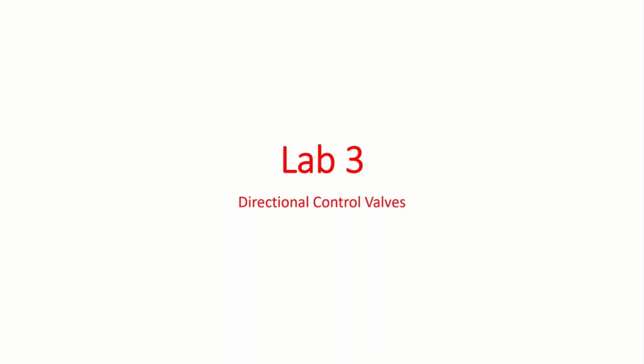In this video we are going to discuss valves with a special focus on directional control valves, and at the end of this session we will look at directional control valve inside FluidSIM, and we will design again a simple circuit in which we will have a 5x2 directional control valve which is going to be used for controlling a double acting cylinder.